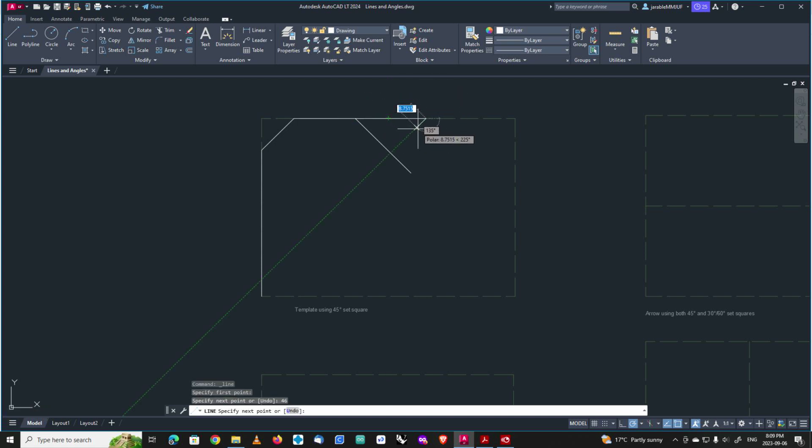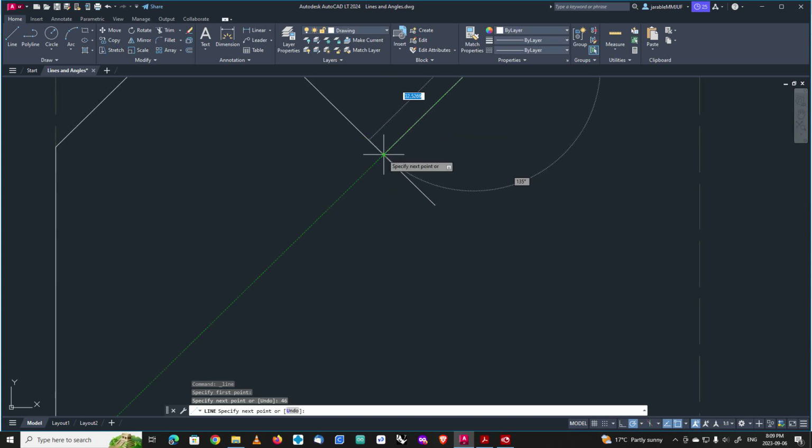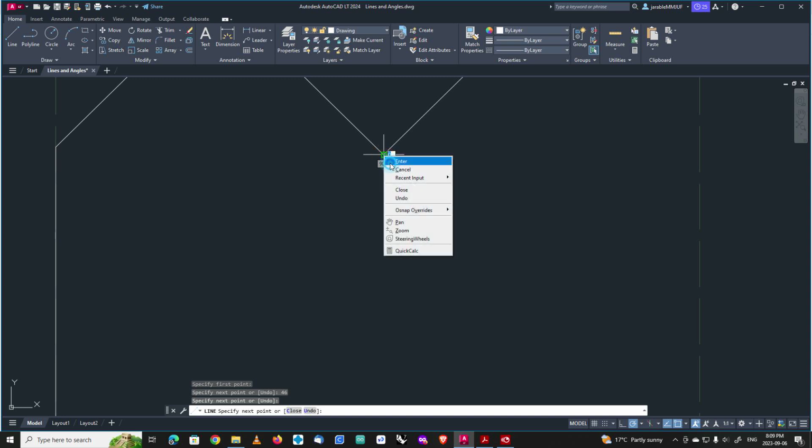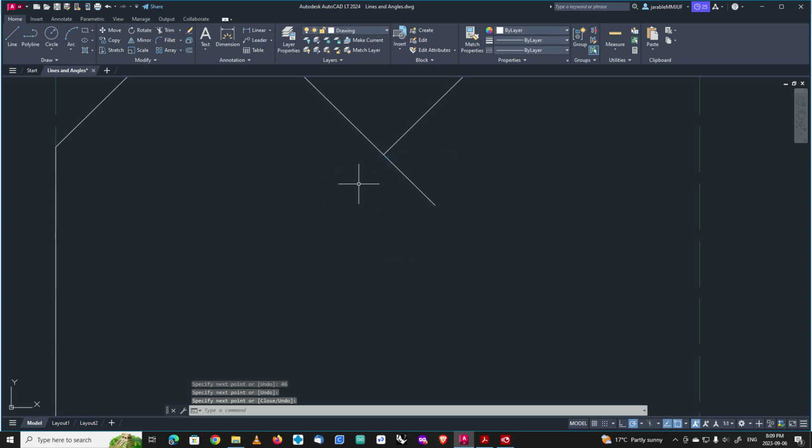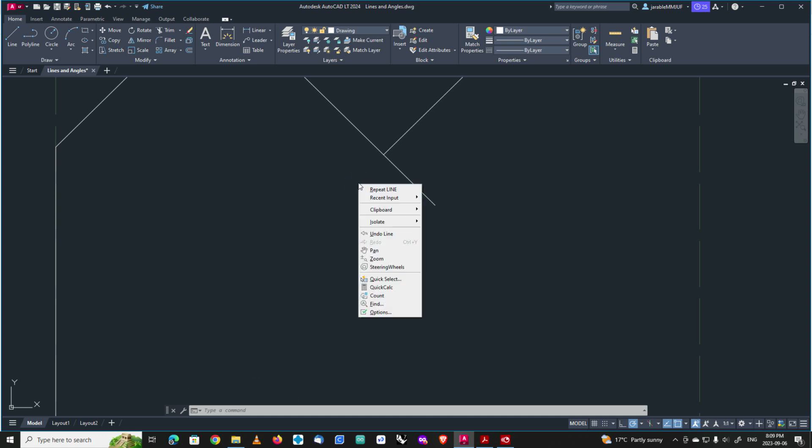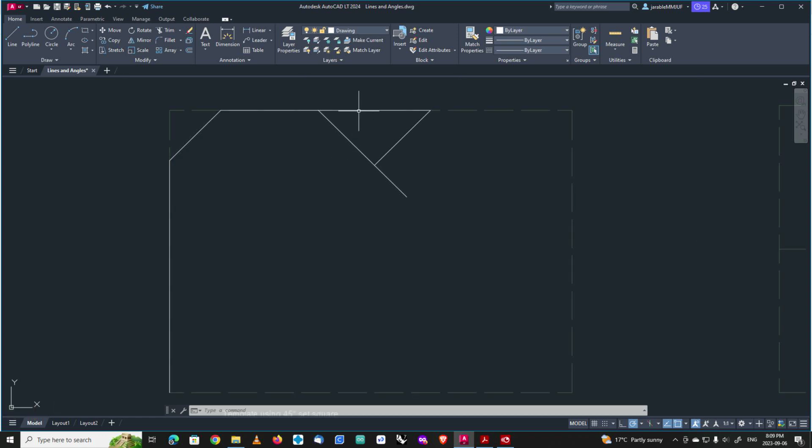Okay, so now I'm going to use my polar snap, go down at a 45-degree angle, and if I can, snap to that and press enter. By the way, I'm not using the keyboard to press enter. I am pressing down the right mouse button, and I can also get enter on that. Okay, so now I can just select this bit of line and delete it. That goes away. Now, I don't want to completely delete this entire line. I just want to trim it.